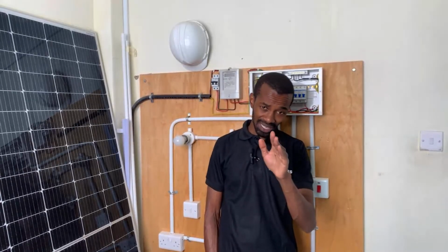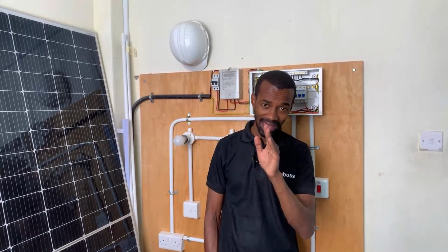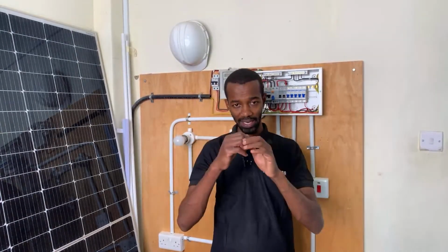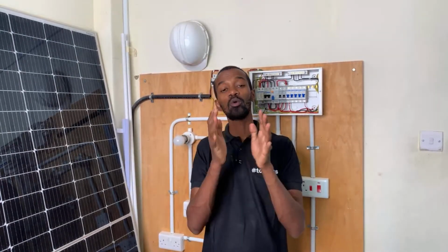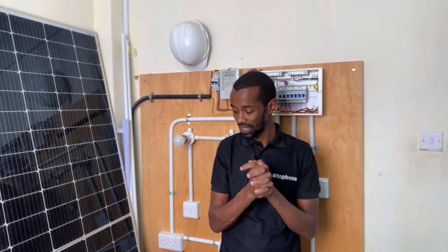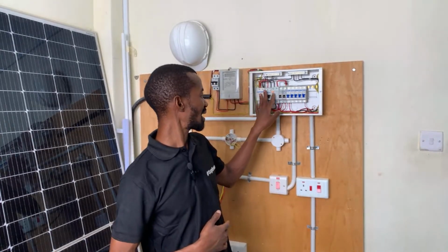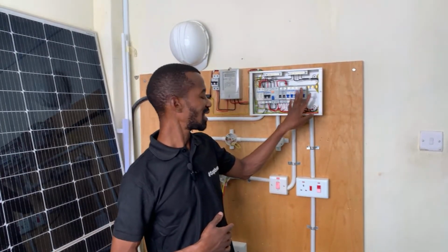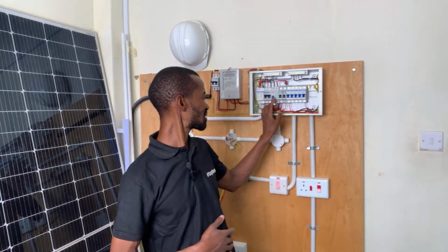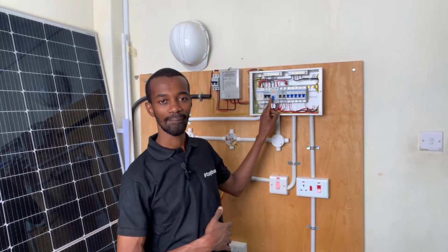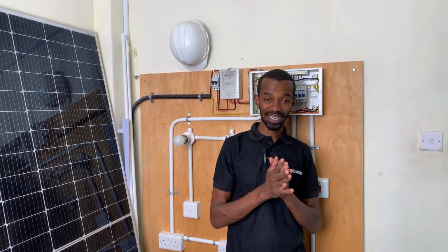And the person in the bedroom where the RCCB does not cover, or it was not wired, then they have a problem. So the wiring of the RCCB plays a key role in protecting the users in a home. If the entire home electrical installation passes through the RCCB, it means that even when there is an issue with the lighting, the RCCB will trip.